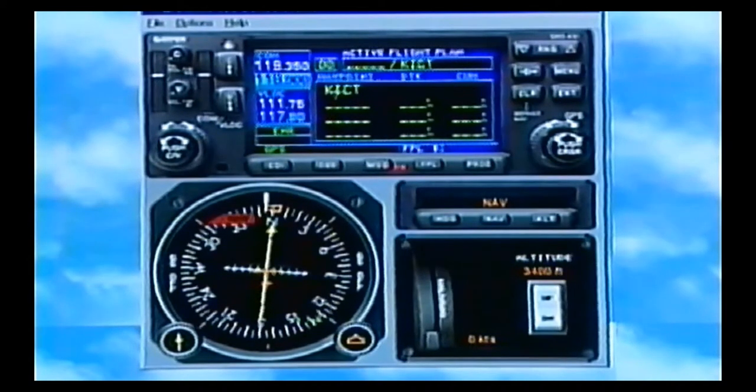If you look, it already has Wichita in there, the airport. If you want to create a flight plan in your active flight plan and you haven't done a direct to, it'll put in your departure airport automatically. So we save you one button step. So now I want to add on to it. I want to go to Wichita VOR, then up to Emporia, and build the airway in there. So I press cursor and just start scrolling it in.